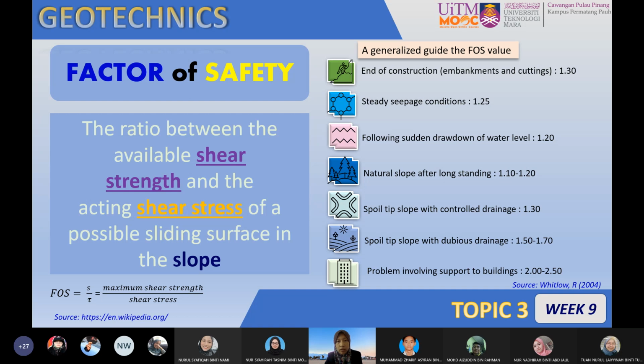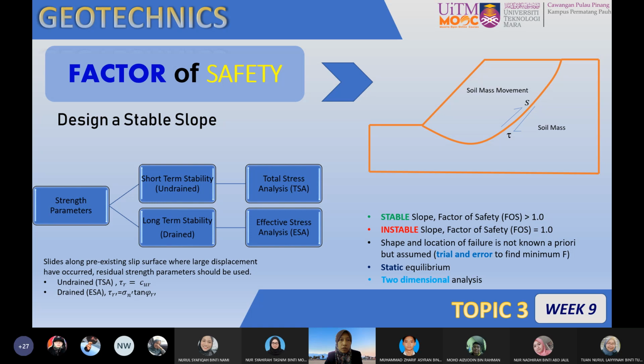Why was the FOS for the foundations of buildings higher compared to other cases? Because of the additional loads that you apply on the foundation itself, and if the foundation lies on the hilly sides, the value of FOS must be taken larger compared to the other applications.